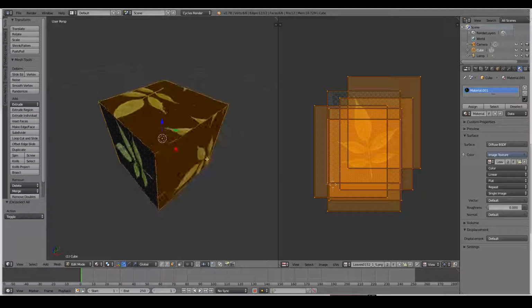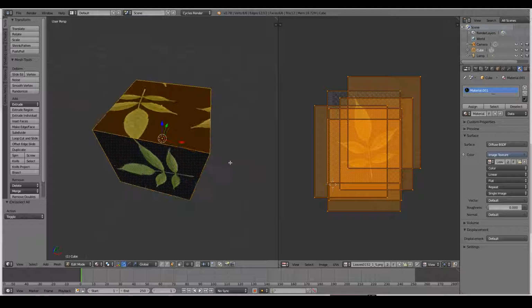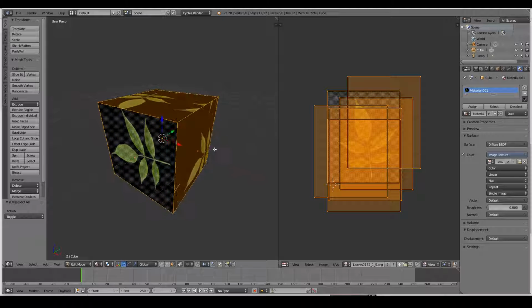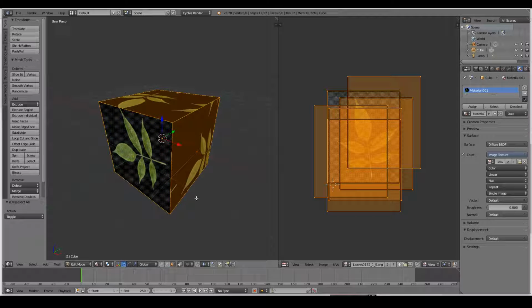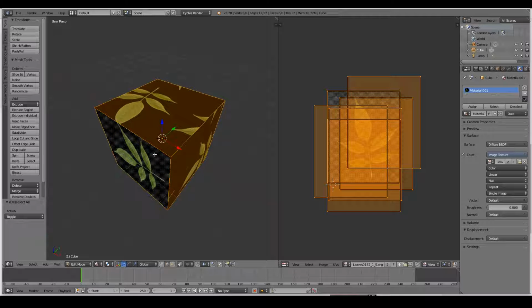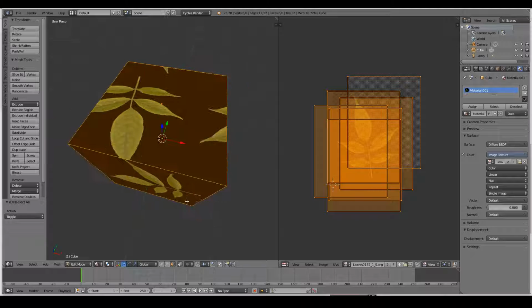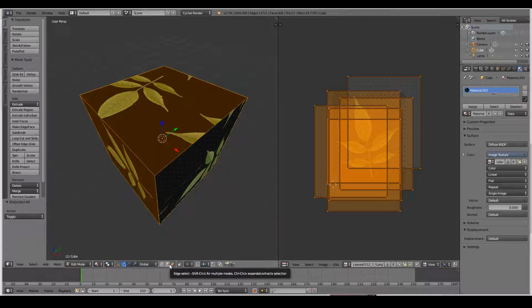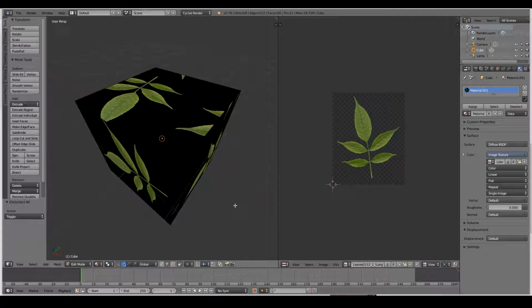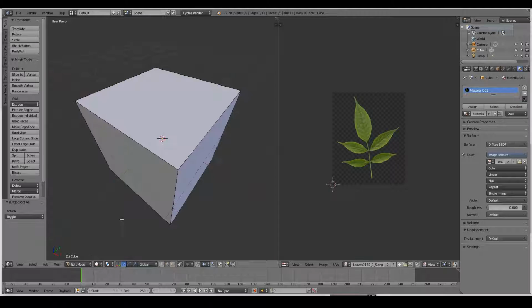So usually you would have to create seams. Seams are pretty much like telling Blender to use the scissors to cut at only these locations. For example, let's try to create a perfect cut of our model where our object will lay flat on the ground but connected. We just want to have this as one solid piece. So we have to create seams. I'm going to go into the edge select mode. Let's now start creating seams. I want to be able to see my object better, so I'm going to change back to solid.